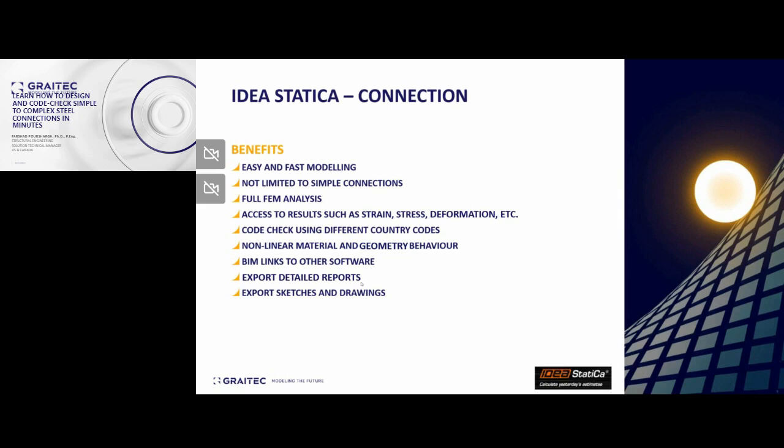As well, IDE Statica has links to other software. So for example, if you have created your geometry in other software like Advanced Steel or Revit or Tekla and newly added STS2, you can actually import the geometry of the connection into IDE Statica and start to add your loads and analyze the connection.